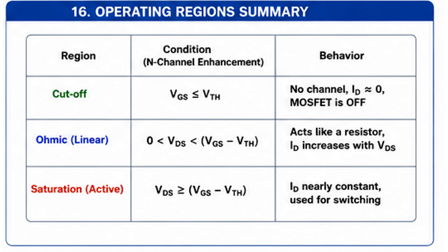When the gate is at the same potential as the source, the region under the gate remains P-type and no continuous N-channel exists. The device is off. As the gate voltage is raised, an electric field attracts electrons toward the surface. When the gate-to-source voltage exceeds the threshold, the surface inverts and a thin N-type channel forms, linking source to drain. Current can now flow. The higher the gate voltage above threshold, the more electrons are attracted and the lower the channel resistance becomes. The relationship between drain current and the 2 voltages, VGS and VDS, defines 3 operating regions.